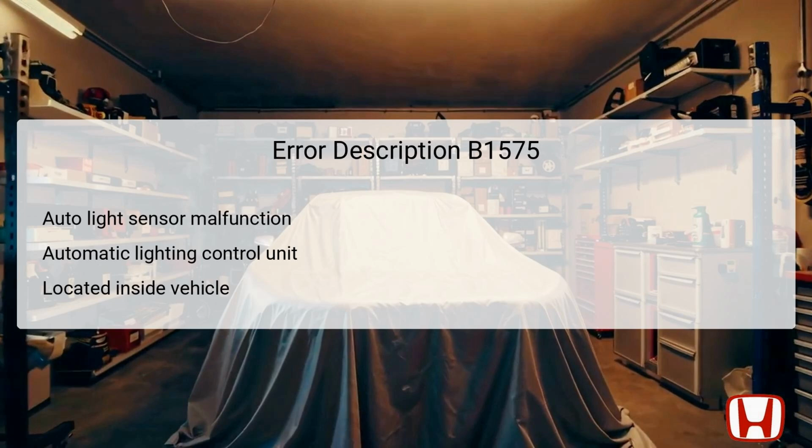The DTC B1575 represents an auto light sensor malfunction that affects the vehicle's lighting functionality. The auto light sensor is crucial for enabling the automatic operation of headlights based on the surrounding light conditions. It ensures that your headlights turn on at dusk or in dark environments. The automatic lighting control unit, typically situated in the same area as the interior fuse relay box, regulates this sensor's operation. This unit processes inputs from the auto light sensor and activates the headlights as required.